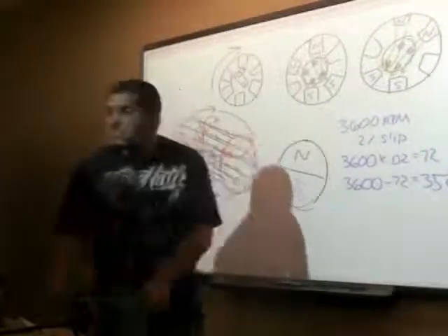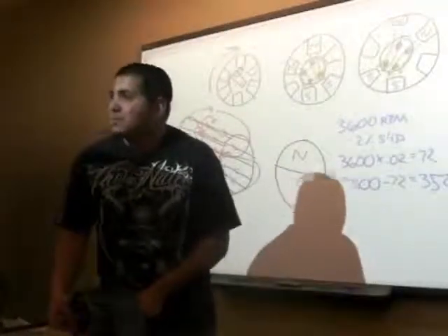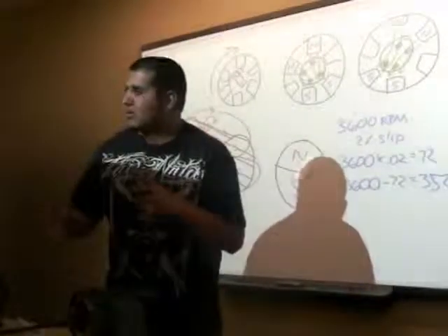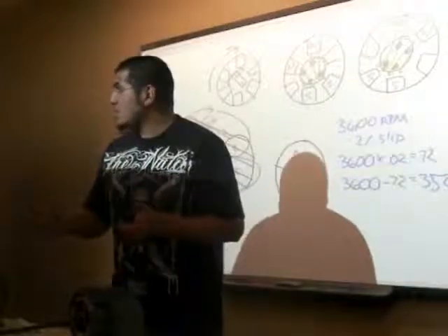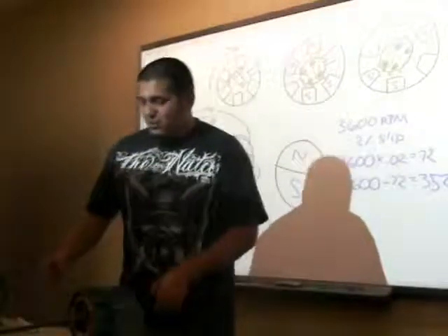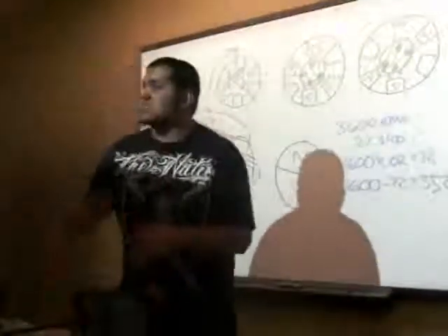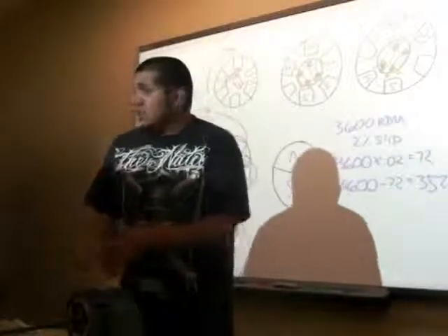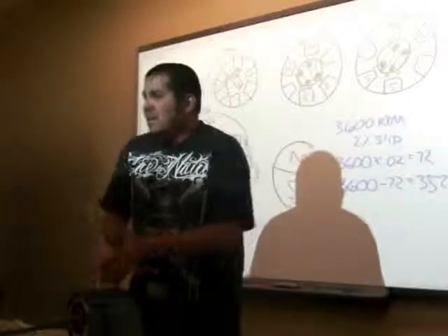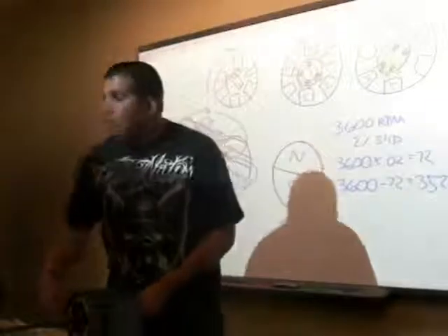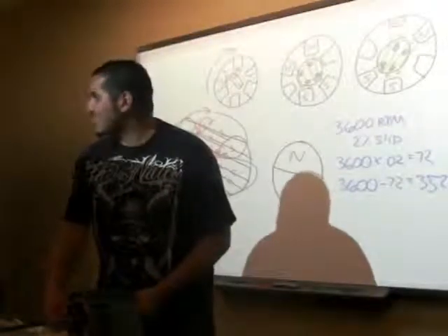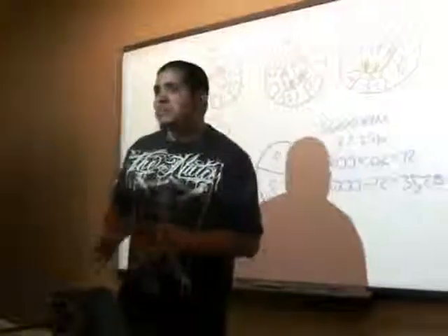So that's why an induction motor can run. You put a load on it, and it's going to slow down, but you probably won't even see it slow down. It's going to react right away, right? Because as soon as you try to slow this rotor down, it starts inducing more current onto the rotor, which automatically, it's automatic, starts to increase the torque, right? Our torque begins to increase here. So it automatically responds to the load.